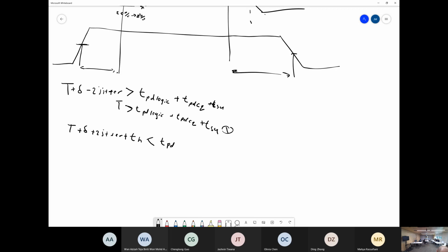Now, I can't remember if you touch contamination delay. I think so. Never mind, ignore this. This doesn't matter for you. Okay, cool. That's all you need to know. So your propagation delay, the amount of time you run your clock, has to be longer than the time it takes to go through your logic and through your memory elements, and to have your memory elements set up.